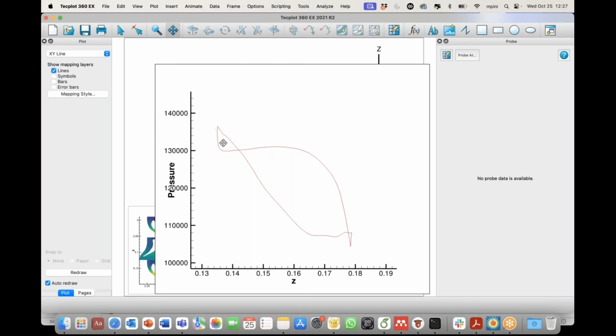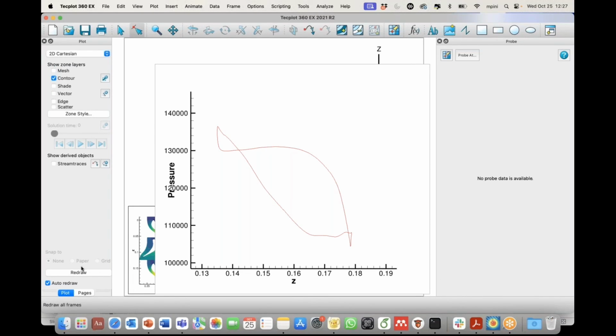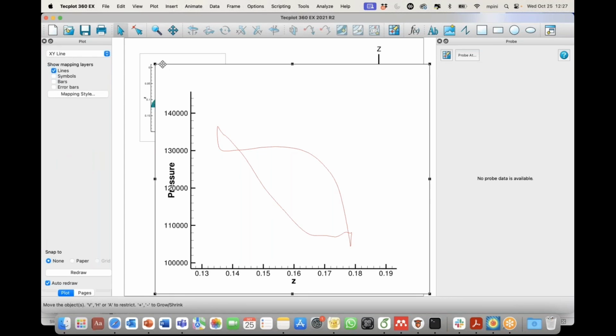We can easily spot that there's something that is not working great with our second stator, because we see that the pressure side and the suction side distributions are intersecting, meaning that this section is basically not contributing to the lift. And this is usually the effect of an incidence or the stagnation point not placed where it should be. And this is something that we can easily see if we look at the original chart that we made.